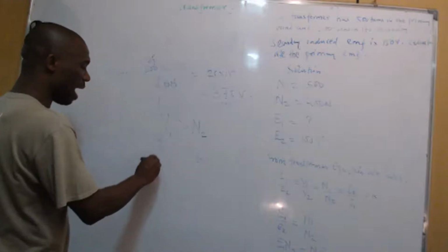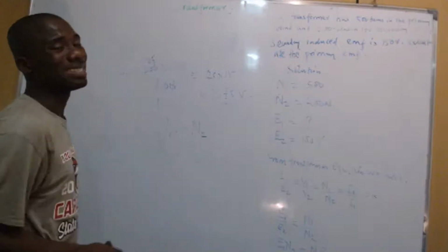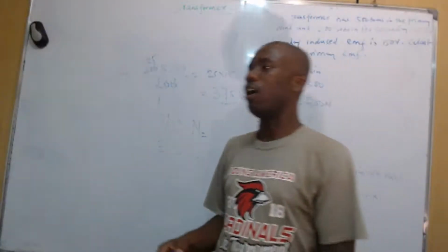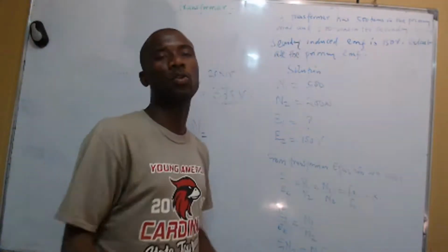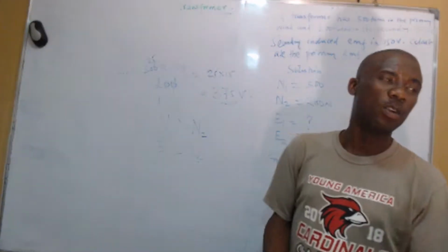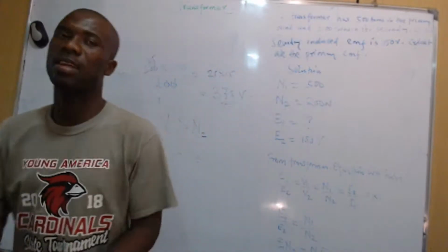And that also means that I1 will be much bigger than I2. So we call this situation a step-down transformer. Conversely, when E2, N2, and V2 are bigger than the parameters of the primary, we say it is a step-up transformer. That's how the system works.